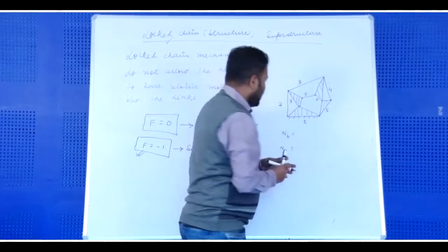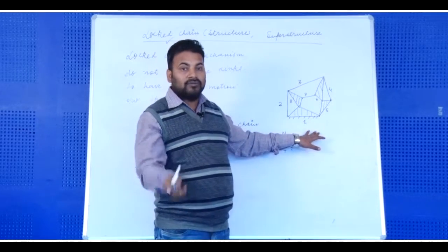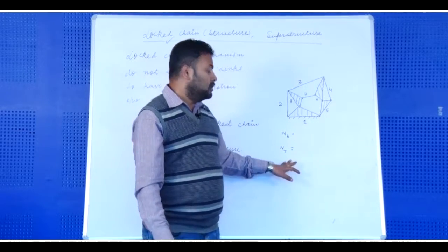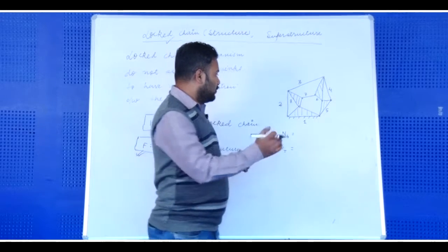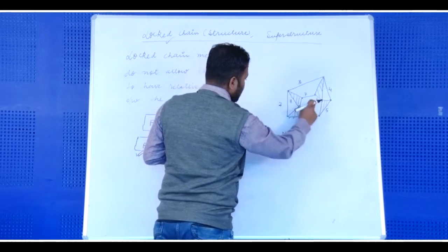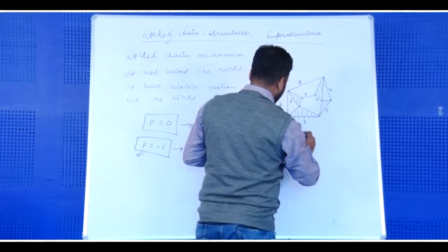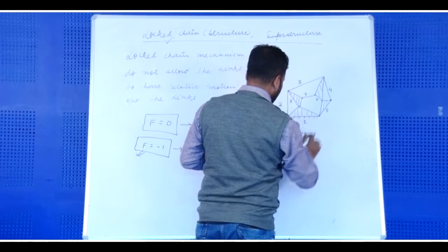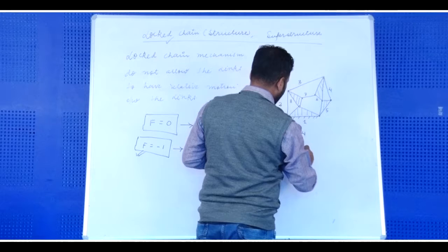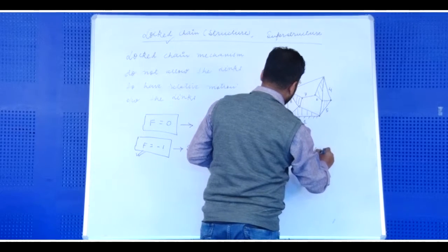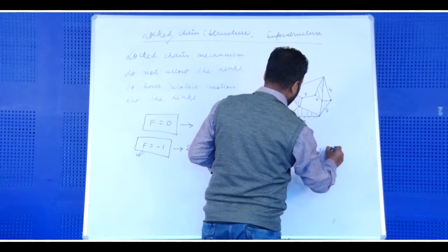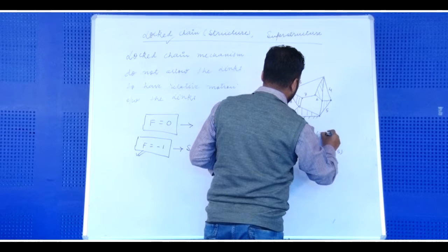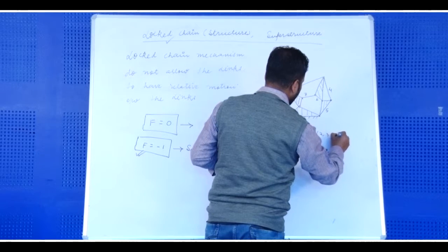As I have told you very earlier, binary links are such types of links to which 2 more links can be connected, and ternary links are such types of links to which 3 more links can be connected. The binary links are 4 in number, and the ternary links are also 4. They are link 1, link 8, link 6 and link 5, which are the ternary links, and the binary links are link 2, link 3, link 4 and link 7.